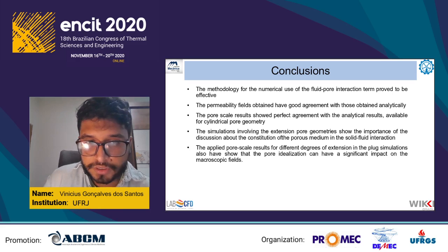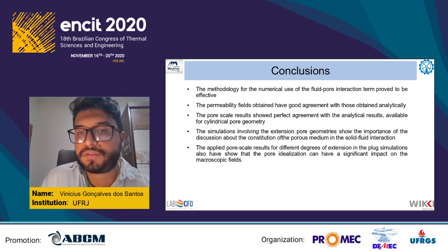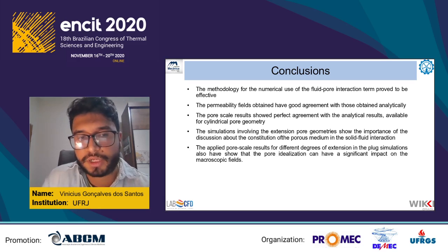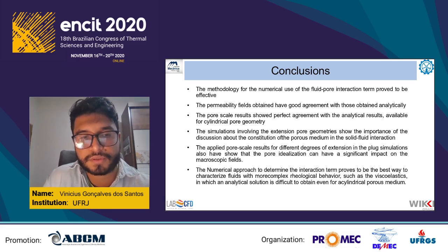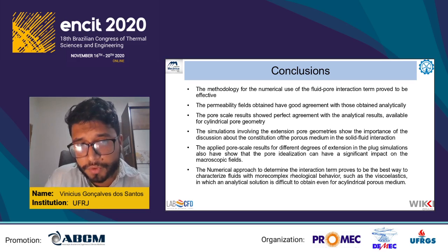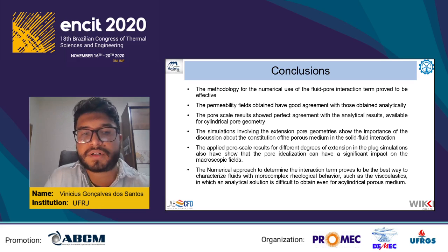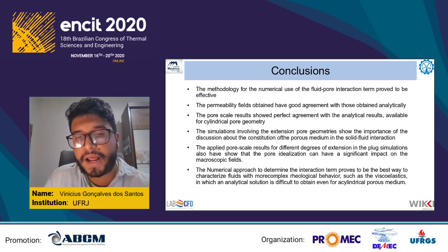The applied pore scale results for different degrees of extension in the plug scale simulations also showed that the pore realization can have a significant impact on the macroscopic fields. And finally, the numerical approach proves to be the best way to characterize fluids with more complex rheological behaviors, such as viscoelastic fluids.